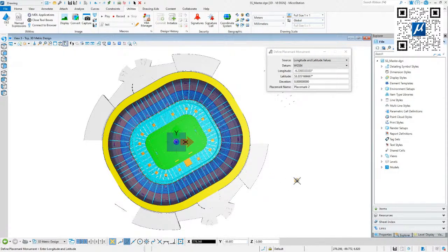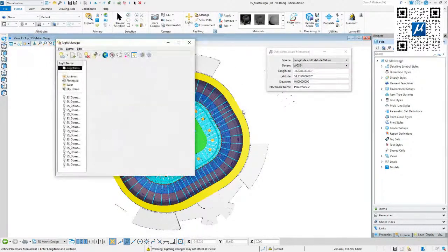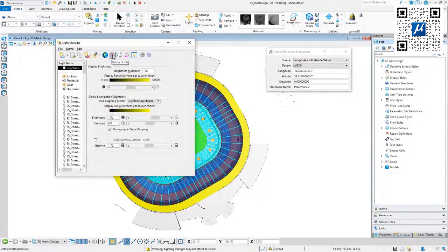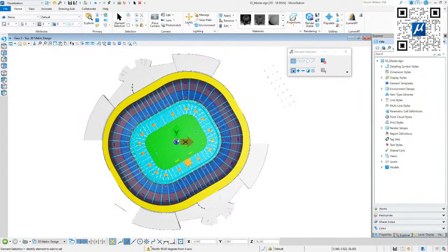The second information we need to know is the north direction. This is something you can set in the background. We have some tools here coming with the visualization tools, and in the Light Manager, there's a Define North option. So I can say the north direction is simply pointing up to the y-axis. Provide coordinates at a certain point that you know, and provide the north direction.